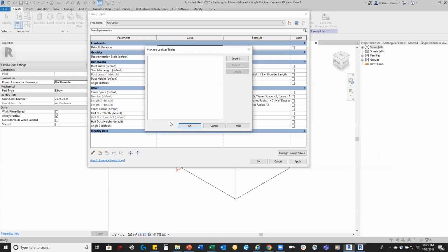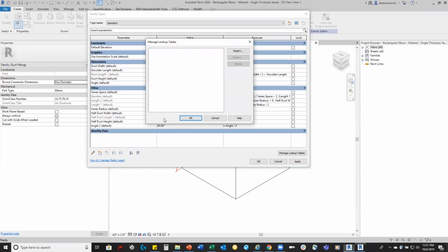Okay. Got a question again about the coefficient table. Guys, you don't get to set up the coefficient table. That's something that's hard coded into Revit. You just have to deal with what Revit has set up. It does come based upon ASHRAE stuff, and like I mentioned, you could go into that TXT file and change that information. But if you're not a computer person, it's tough to make heads or tails of it. It's something I have played with a couple of times and haven't really cracked the code on yet in terms of how it works. There are lots of blogs out there from everybody else who's been trying to figure out the magic behind it.